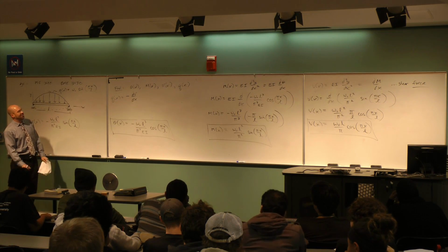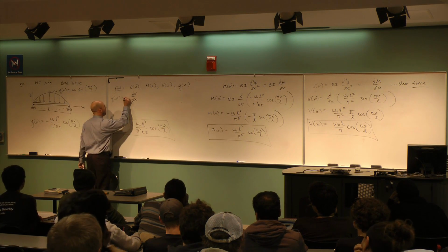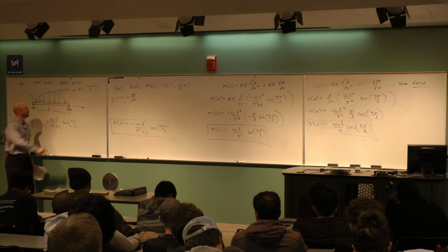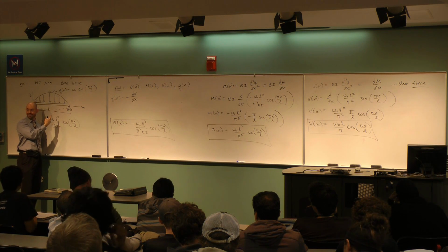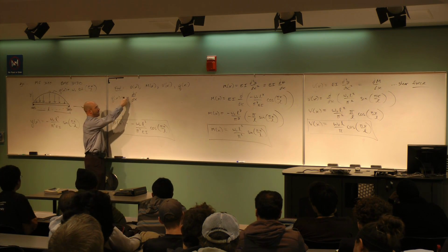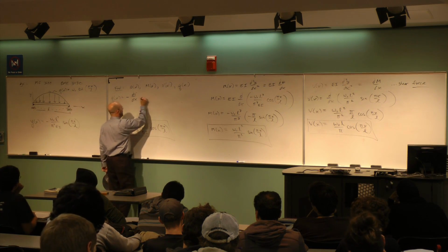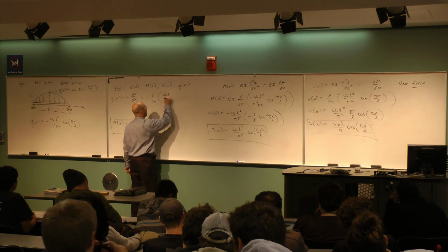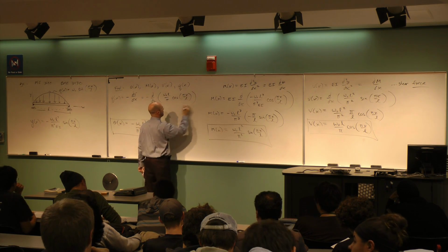All right, so minus dv dx is the definition, and this minus sign just has to do with sign conventions for internal shear force in relation to external load. For example, this load is defined as positive, even though you can see that it points down. It's just the way we chose that definition. If we would have called this negative, then this would be a positive here. Based on those definitions, I put a negative in front, so I need minus the derivative with respect to x of what I just got for v, which is W naught L divided by pi times cosine of pi x divided by L.